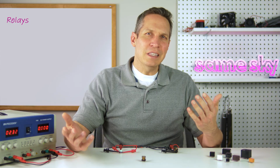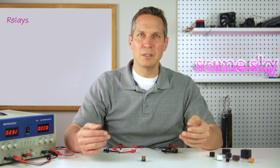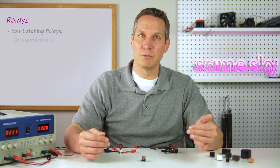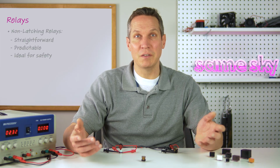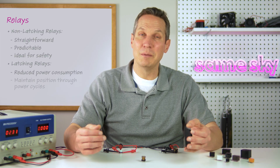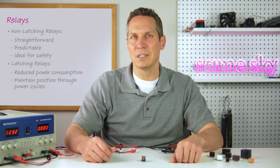And that's it! Relays are simple devices in principle, but selecting the right one and driving it properly makes all the difference in system performance. Non-latching relays are straightforward, predictable, and ideal for safety-focused applications. Latching relays reduce power consumption and maintain their position through power cycles, which is valuable in many modern designs.